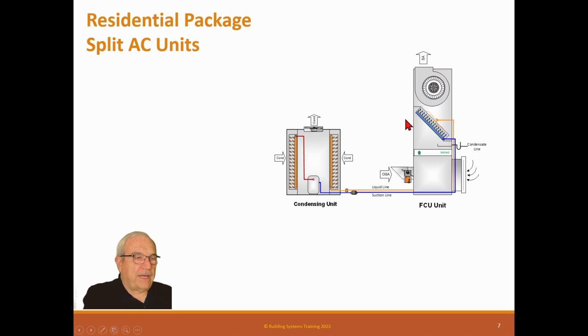When you put a package unit on the roof of a house, when it comes on, you feel it in the house. You can hear it shake because it's transmitting that vibration down through the roof trusses. It's very hard not to have it do that in residential construction.